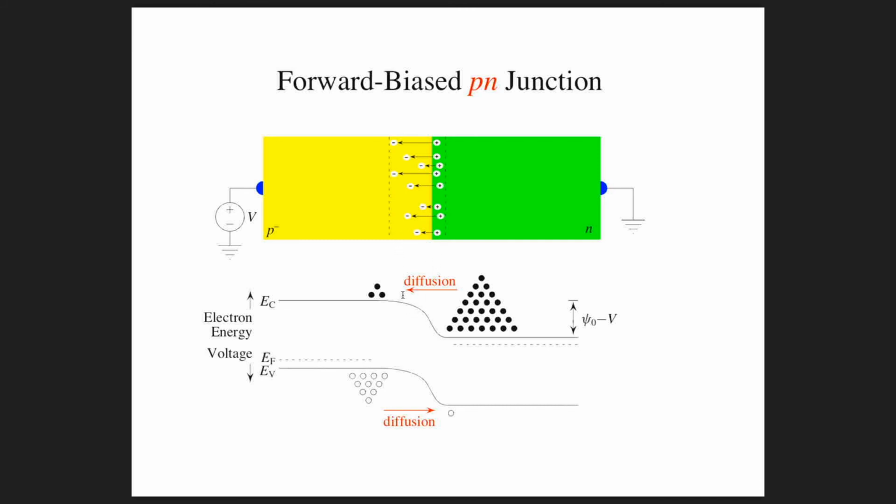field, and that's going to reduce the tendency of the electrons to roll downhill here, to drift, and of these holes to bubble up, and it's going to exponentially increase the number of carriers here that have enough energy to go this way. And so the diffusion current is going to be greatly accentuated. Now, of course, because there are so many more electrons here, most of this diffusion current is going to be electron flow, but there's also a small amount of hole diffusion current in the opposite direction. So we're going to get an accentuation of diffusion and a suppression of the